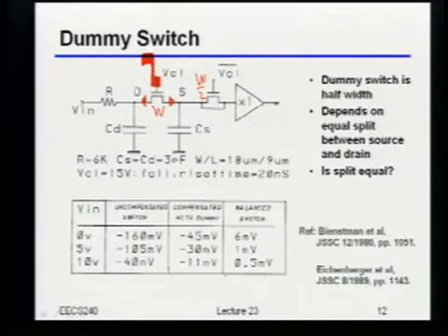There we go, the impedances, right? Because let's say I had 0 impedance right there and an open circuit right there. Well, clearly, all the charge is going to flow into the 0 impedance, right? So in fact, in order to make this work, what the people who originally came up with this actually tried to do was intentionally muck around with the circuit to force the impedance to be the same on the two sides. Okay, so you can see they added this CD right here. And the whole reason for adding that CD was to make it so that the impedance on the left side looks similar to the impedance on the right side where we have this sampling capacitor. In fact, not only that, this is my input voltage over here. So if that had too low of an impedance, then a lot of the charge would get sucked out over there, and you wouldn't know how big to make this dummy switch. So not only that, they actually even added an extra series resistance here.